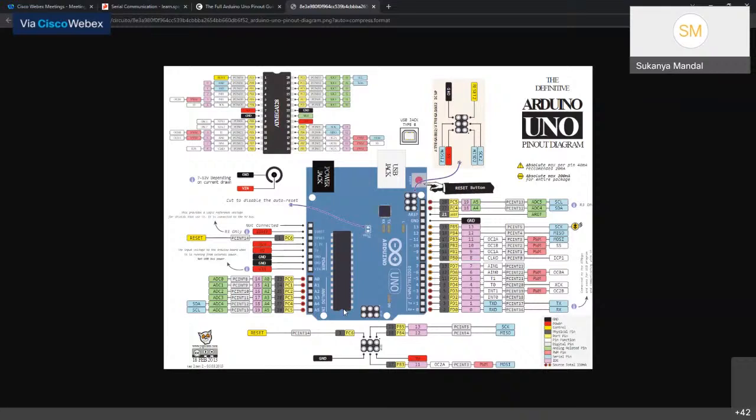And one thing to remember is this notch is basically where pin numbering starts from 1, right? And then it goes 1, 2, 3, 4, 5, 6 until 14 here, and then it starts from 15 until 28 here. The pinout references are given here. So the Atmega is referenced in these pinouts. This is the microcontroller that is the brain of the Arduino Uno, and these pins are useful for connecting your sensors or any other devices that come across.